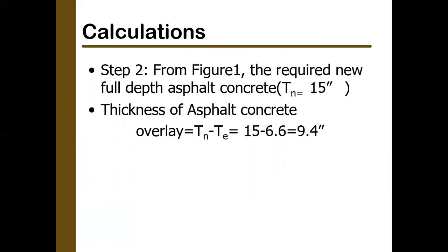Now, this is 9.4 inches. It means you can say that it will have 2 inches of asphalt bearing course and 7.5 inches of asphaltic base course. So this is how you design an overlay using the component analysis technique, and this also ends our first part of this overlay design.